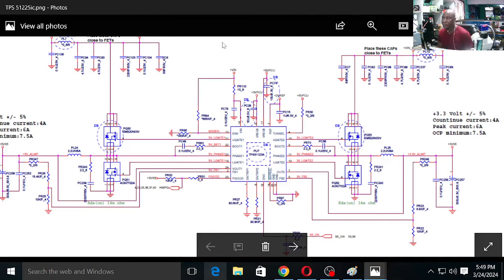You see this. We have 4 outputs here. We have the VREC 3 and VREC 5. So the SIO or the startup chip is not getting power from this output. It's getting power from this VREC 3. If you check with the test meter from this point, the startup chip is getting power from this 3.3 volts.